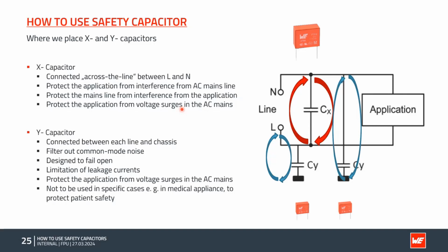The Y capacitors, as you see here, are connected between each line and the chassis. They filter out common mode noise. The X capacitors do the differential mode noise.